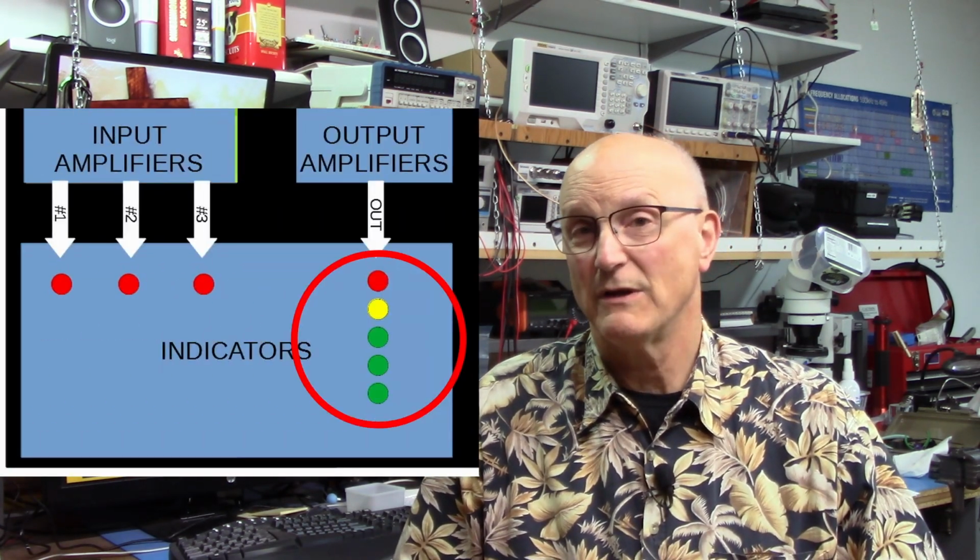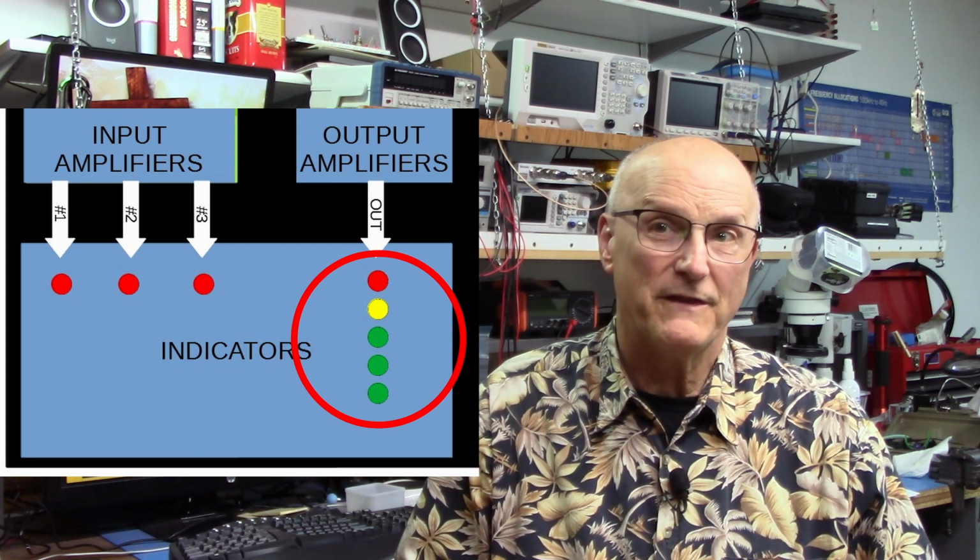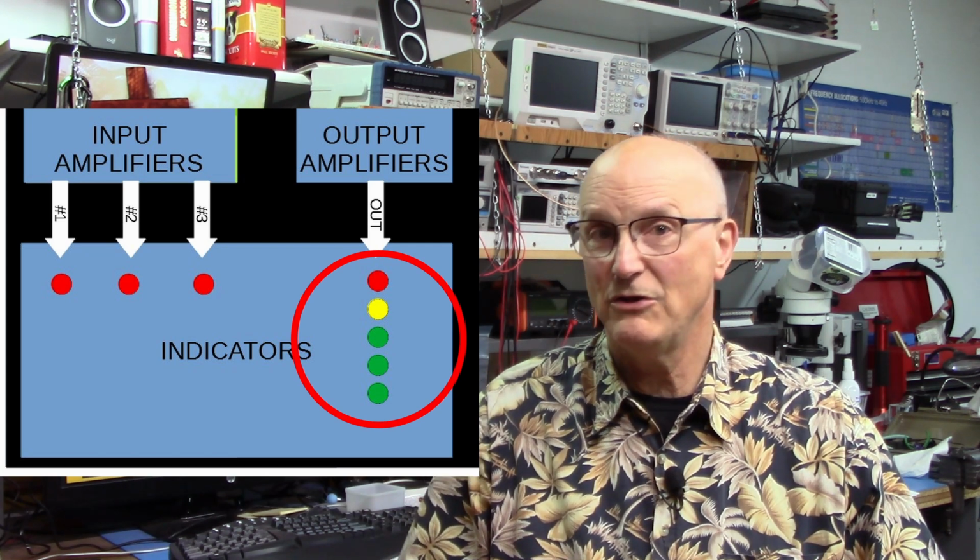In the intervening days, the software guy spent some time, well, a lot of time, working on the actual software to do the task. I mean, why design in a device that can't do the task assigned to it? This is where he discovered the complexities of the whole thing. The biggest issue was the output level meter. We thought that this should be in real dBu, which spoke to us of an RMS calculation of the audio.